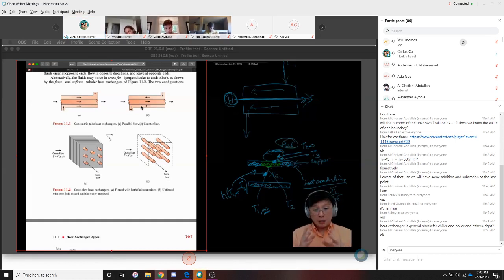So you notice here, if you want to transfer heat from one fluid across a pipe material, you have some metal separating the two fluids, followed by another fluid, so you have three elements of heat transfer. You have convective heat transfer from fluid to the pipe wall, conduction from the inner pipe wall to the outer pipe wall, so that is thermal conduction. Then you have another heat transfer coefficient by convection from the outer pipe wall to the outer fluid temperature. And so you have to somehow combine these together. You want to have an expression.